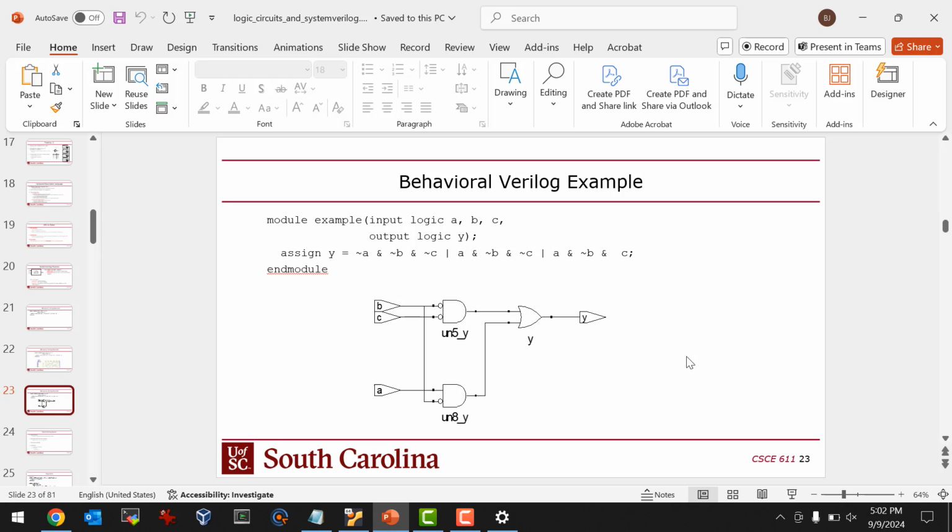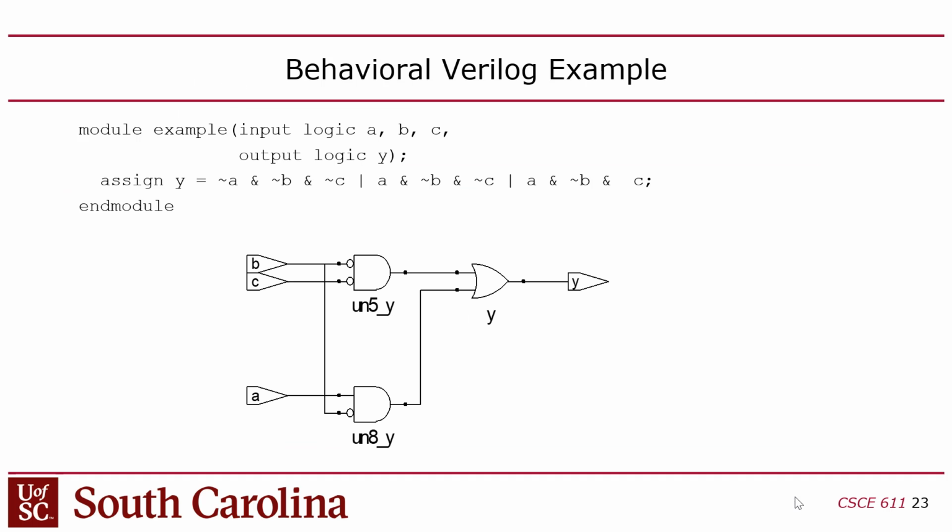So here's a slide that's kind of cool. This came from the book. Now notice that QuestaSim, they changed the name, QuestaSim, which is this thing I was just using, won't show you the structure, right? But if you take that code and you put it in Quartus and you synthesize it, you can actually have it show you a gate level depiction of the structure, right?